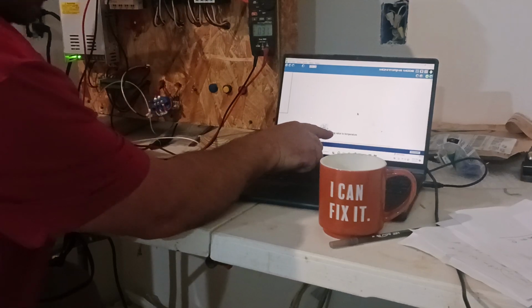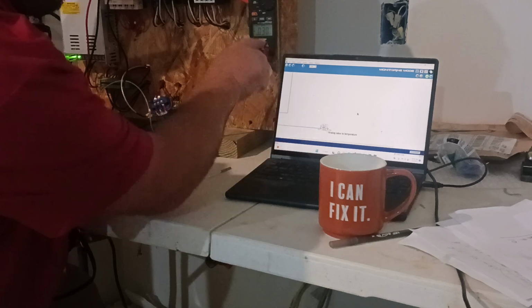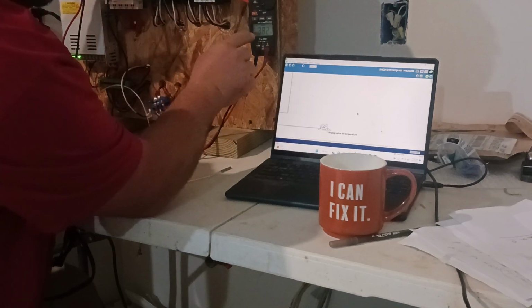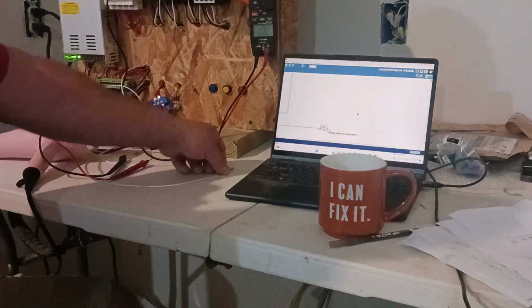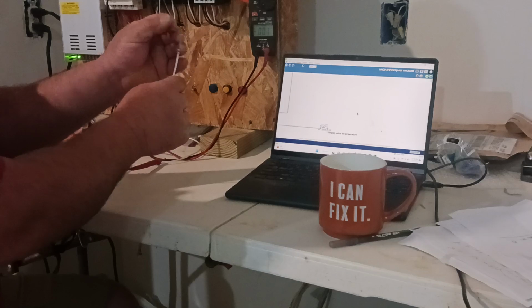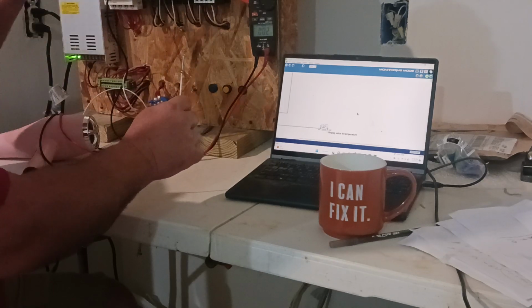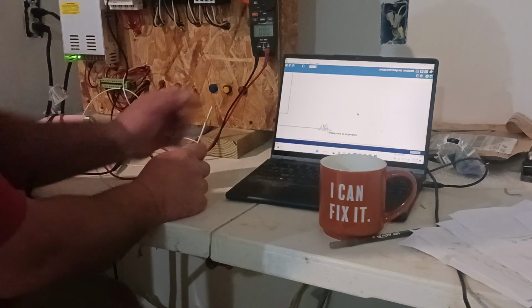You see my temperatures, so my analog value is 97, my temperature value is 114, and my voltage, if I keep it on the leads, is 3.82. So hopefully you've noticed the temperature sensor senses the temperature and sends a signal which is a little bit higher or a little bit lower voltage depending on the temperature, which can be scaled.